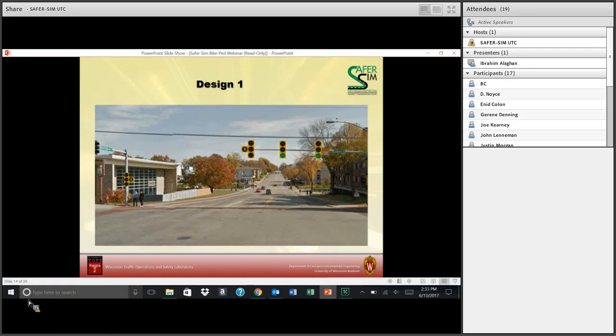So what we have done, if you see it on the left side of the intersection, we made it to the right of the traffic signal itself, because we don't want the driver or the pedestrian to be confused by this sign. The pedestrian may think it is a sign for him or her that now they can go and so on. So yeah, if you go to the next, please.